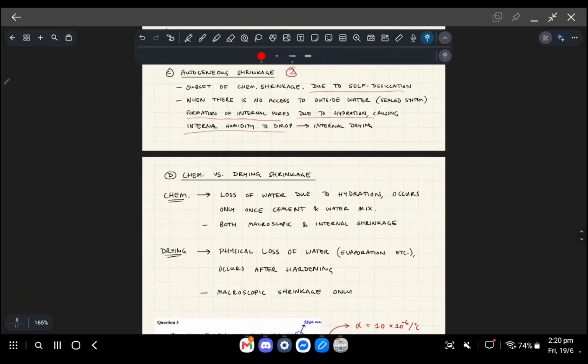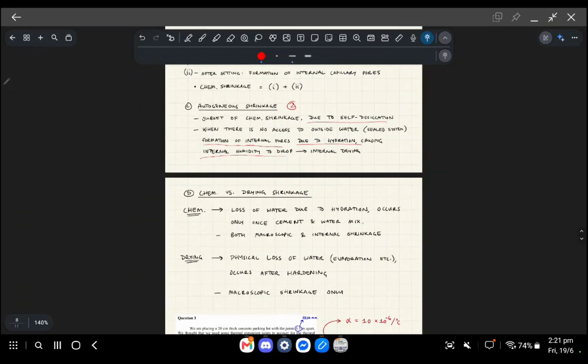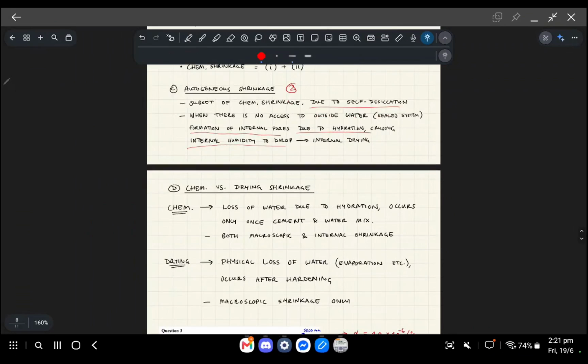It's kind of confusing to me because it's not the way that I would word it. My understanding about everything is, there's drying shrinkage, which once again is just the physical loss of water. Then there's chemical shrinkage where water is consumed in the reaction, leaving voids, not air pockets, but just bubbles in the cement. And then there's autogenous shrinkage, or however you say it. That's just internal drying. So all of the processes are just different ways of losing water.